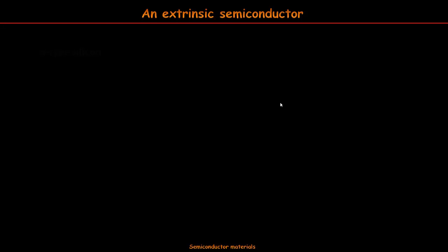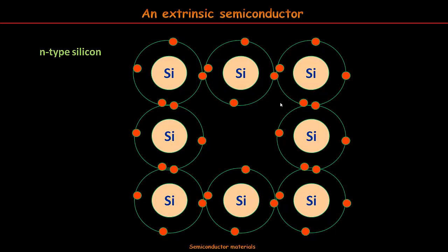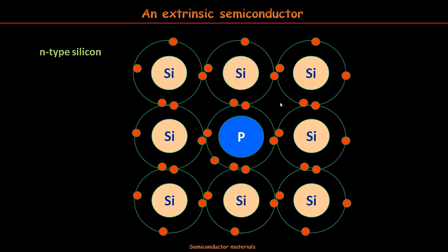Let's begin with the N-type silicon. By diffusion, some phosphorus atoms, for instance, can make their own room among the silicon atoms in the network. Then, 4 of the 5 electrons in the last layer of the phosphorus atom make covalent bonds with the surrounding silicon atoms, but the 5th one is not bonded, and it can easily be freed to move along the material. Now there is a new electron with no associated hole left behind. Then an N-type semiconductor has some free electrons moving in the network.